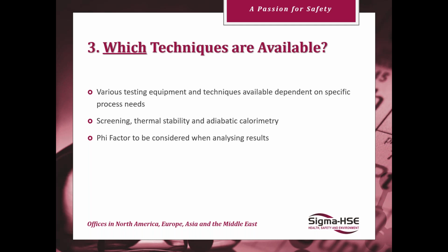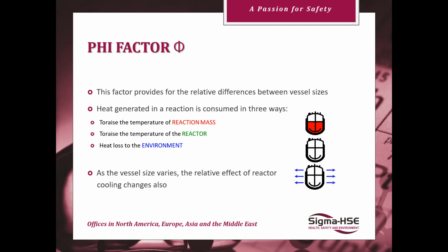Coming back to the size effects, I'll go into what the phi-factor is in a little while, but the phi-factor needs to be considered when analyzing results. So here we are, phi-factor. This factor provides for the relative differences between vessel sizes. As we've seen, as you scale up, cooling and heating effects react very differently depending on the size of your vessel. So this phi-factor really neatly allows you to correct for that.